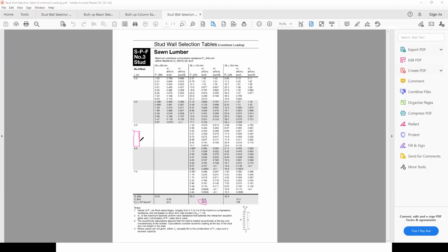So therefore, if I have 3 studs, what happens is that it's 1/12 the base times the height cubed. Since the base is linear, and this is 3 times, I could just multiply this value by 3, and that's going to give me the same value as if I would use the equation. That's why I'm allowed to do that, because it's the B that changes, not the H. If it was the H that changed, I cannot do this, okay? Keep that in mind.